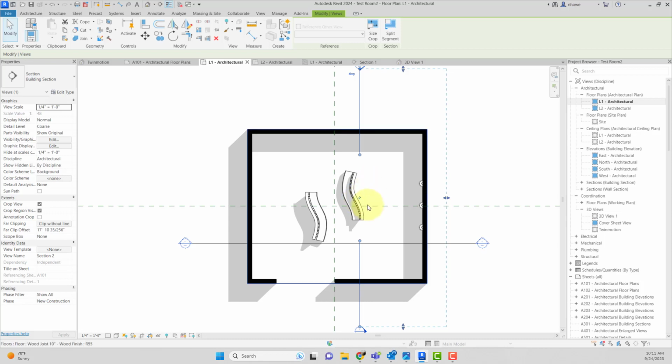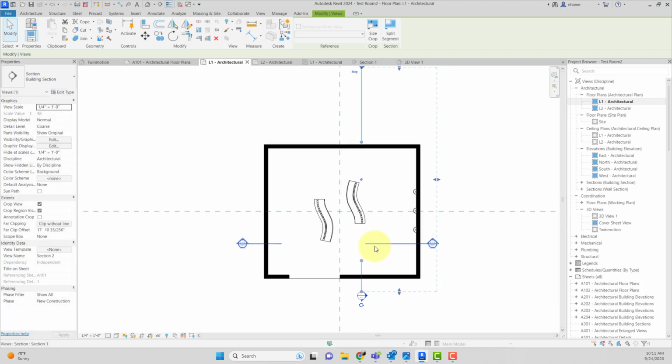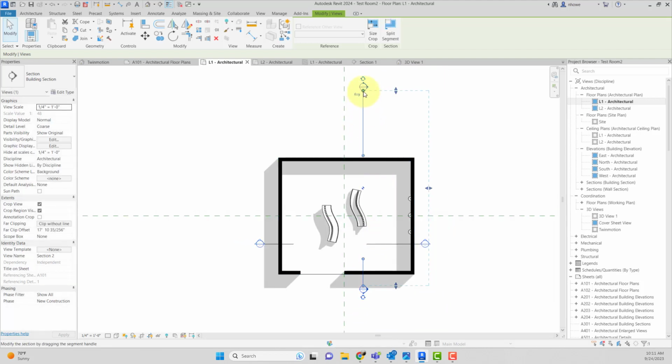One thing on wall sections, please break them. Right there, you can see what I'm doing. It is bad form to have your wall section line go through the entire plan. The reason for that is that it looks like it's an actual object when you do that, as opposed to being a symbol. So cleaning up your section lines is important, and something like this would be good.